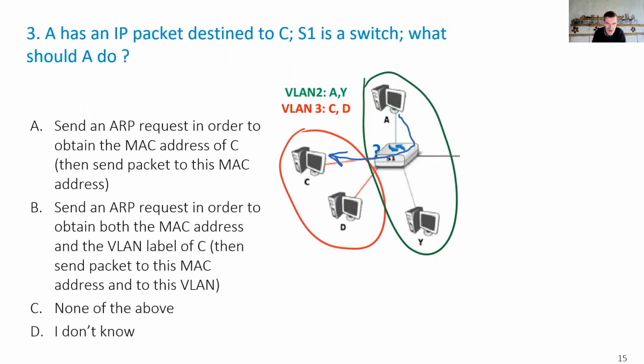Virtual LANs. Here I'm assuming I have a switch, and there are virtual LANs. Virtual LANs are also very often used in substation automation, because by being only at the MAC layer, we have lost all the flexibility of the IP layer. And part of this flexibility we regain by creating what are called virtual LANs.